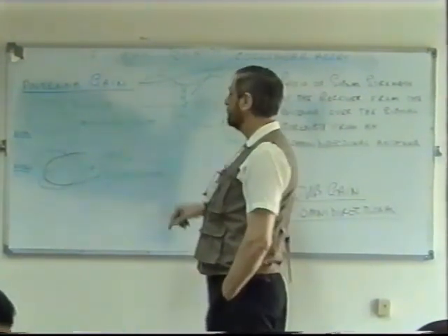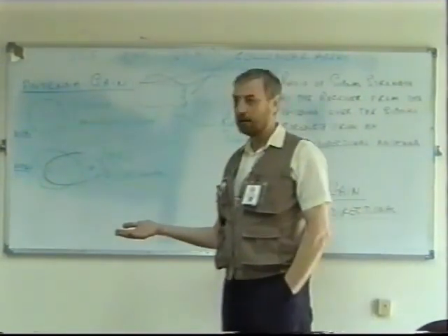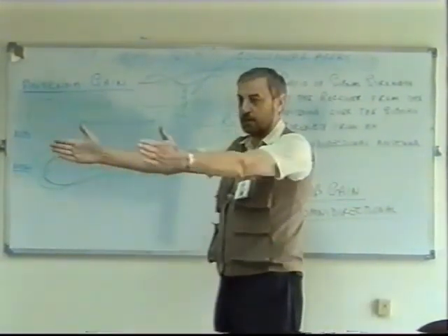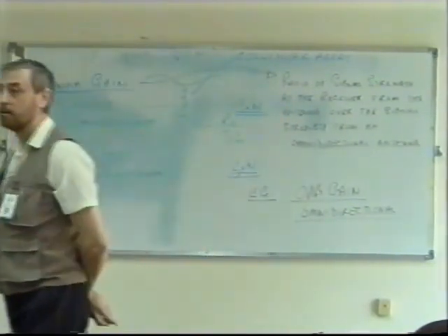But be very careful. If somebody says they've got an antenna which is 25 dB or 30 dB, then they must also be concentrating the beam this way. With a very high dB, it is not only directional, it must not be omnidirectional. So we cannot use it for mobile. When the dB is lower, I would say 6 dB maximum.